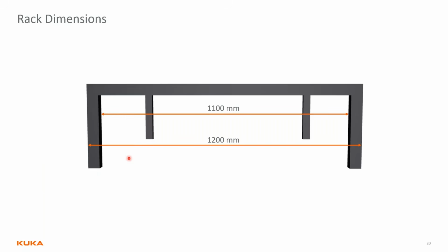That means the legs are 50 millimeters, which is higher than the minimum, which was 40 millimeters. And if we look at the 1500p, which is 900 millimeters wide, and we're adding 100 millimeters for the L3 dimension that we talked about, that's going to give us 1100 millimeters, so we satisfy that requirement.